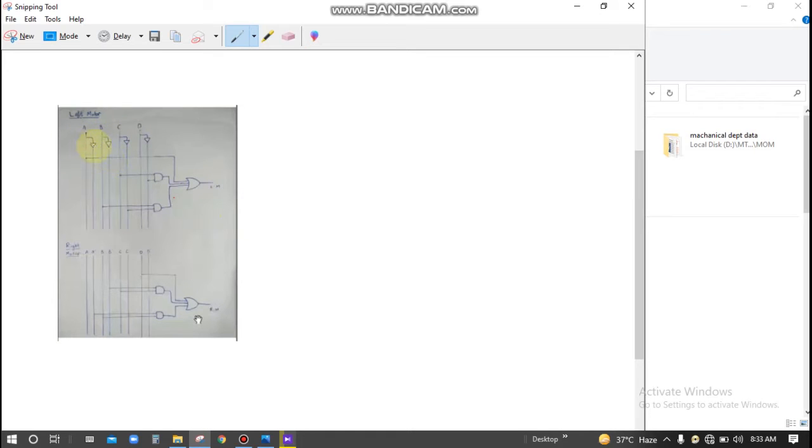These are high and these are low. This is an OR gate that is controlling all these, taking inputs directly from the final equation. This is an AND gate. In this way we have made a combinational circuit. Our theoretical work is now done.